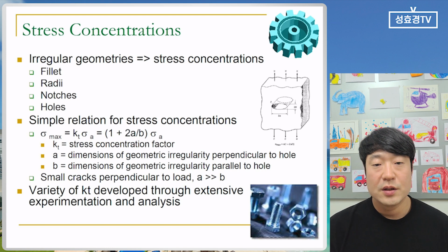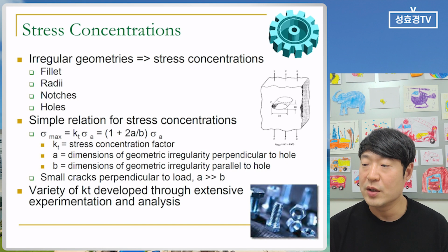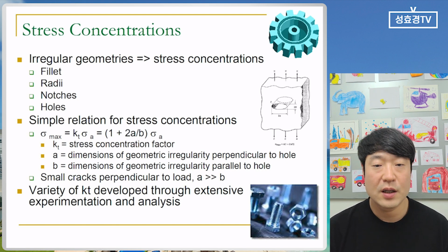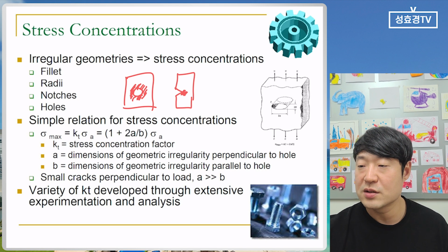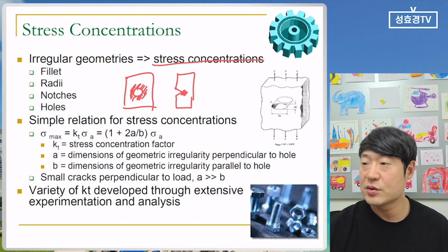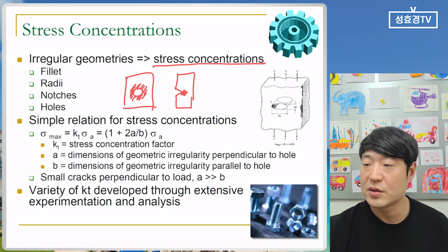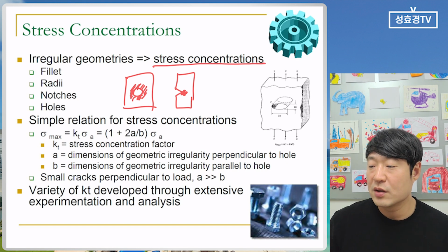And stress concentration is very critical for applications and for parts when we want to use them. There are a lot of things in the materials case we sometimes don't need to consider, but when we make it as a part, sometimes it has a hole inside. So the area surrounding this hole, the stress is concentrated, or if you make a notch, the stress is concentrated. So stress concentration is very important to think about in the industry.